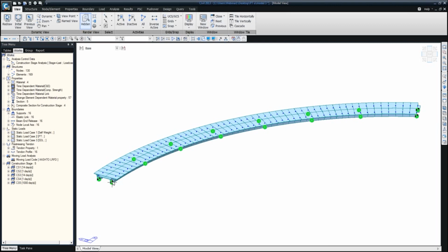So that member is very essential. If dummy elements or the transverse member is not in place, then there is no way that one girder line is sharing load with the other girder line, unless you make this as a finite element model with the webs and deck slab, everything with plate elements. And for concrete bridges, I would not recommend you to use plate elements for webs and all, because there's hardly any out of plane bending occurring in concrete thick girders or concrete webs. They are not like steel plate girders, where that phenomena is quite important.